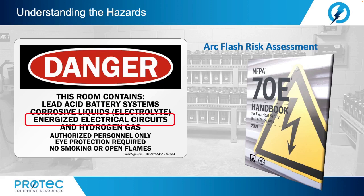Now also, what is the available incident energy at the working distance, or the arc flash PPE category? Personal and other protective equipment required to protect against the arc flash hazard, and what will be the arc flash boundary. All of this needs to be established before work can begin.